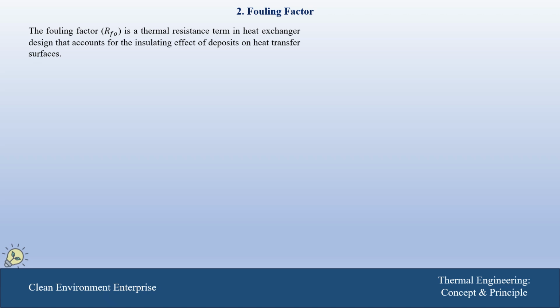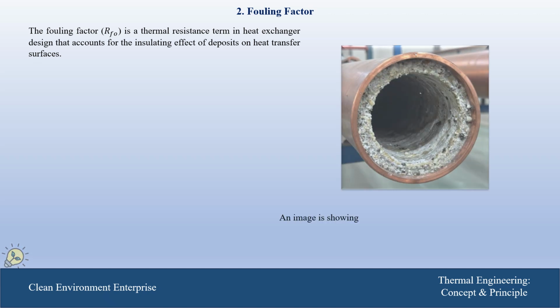So this is an extra resistance to be considered because it accounts for the insulating effect of deposit on the heat transfer surface, as we will see in the design of heat exchangers.